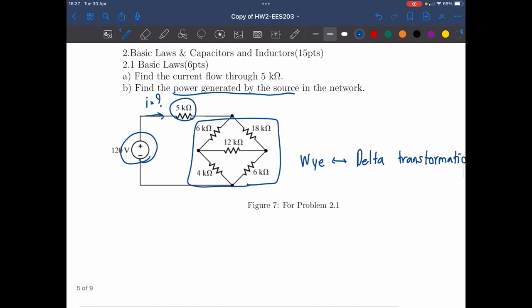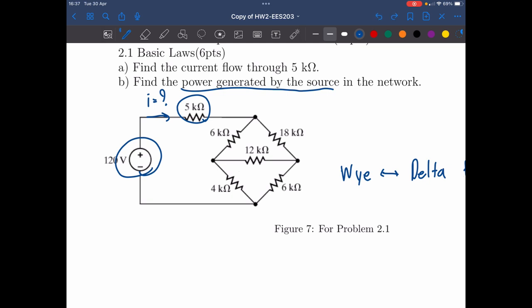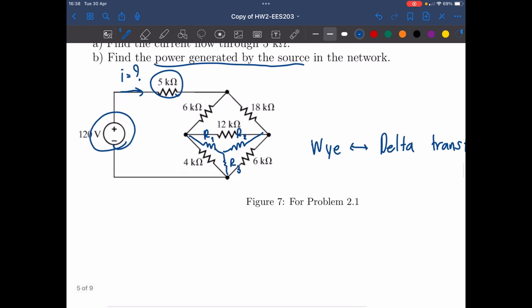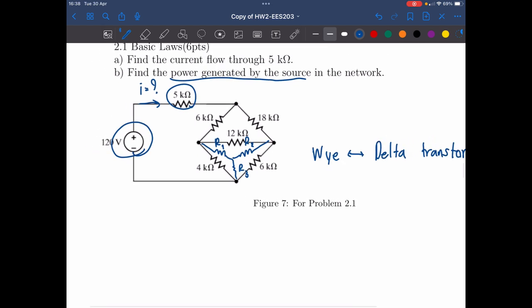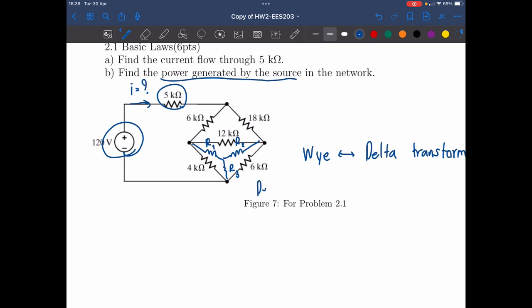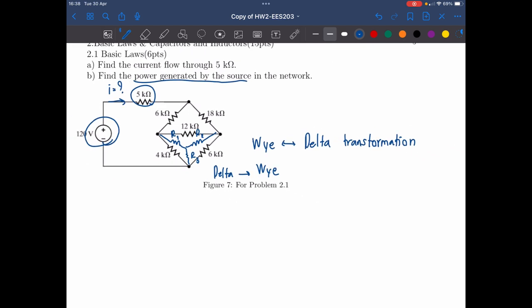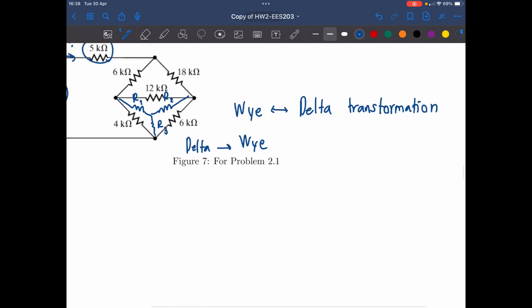And as you can see, if I apply this, I could calculate the total resistance easily, as I'm showing right now, the formula representing this total equivalent resistor in a different form. You see that I'm transforming delta to Y in this case, and the formula corresponding to this case is, let me put it here.